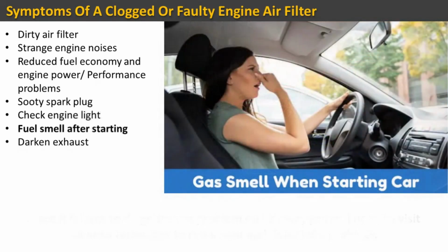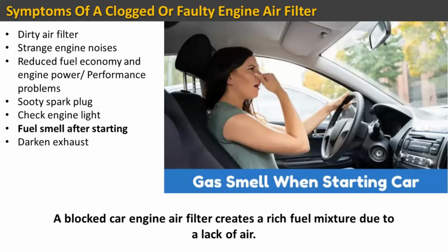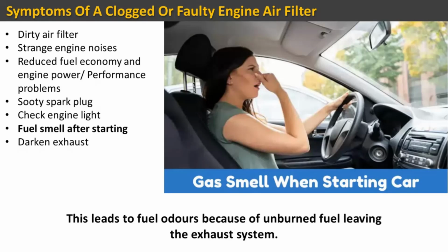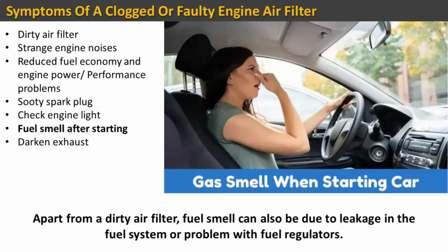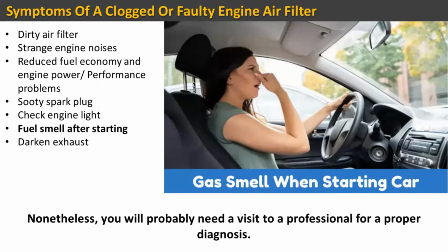Fuel smell after starting. A blocked car engine air filter creates a rich fuel mixture due to a lack of air. This leads to fuel odors because of unburned fuel leaving the exhaust system. Apart from a dirty air filter, fuel smell can also be due to leakage in the fuel system or problems with fuel regulators. Nonetheless, you will probably need a visit to a professional for a proper diagnosis.